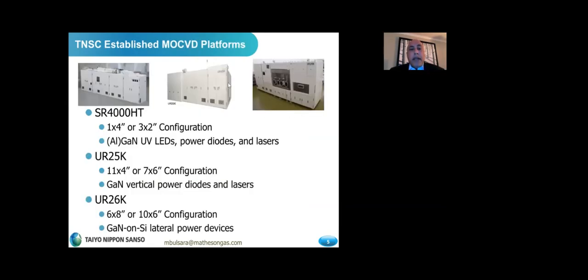TNSC has been making MOCVD systems since 1983. Our first gallium nitride systems were introduced in the mid-1990s, and I highlight three of our main platforms here: the SR4000 HT, the UR25K, and the UR26K. The SR4000 HT has high temperature capability and processes films up to 1350 degrees C. It can process one 4-inch wafer or three 2-inch wafers, and is ideally suited for UV LED applications, power diodes, and lasers.